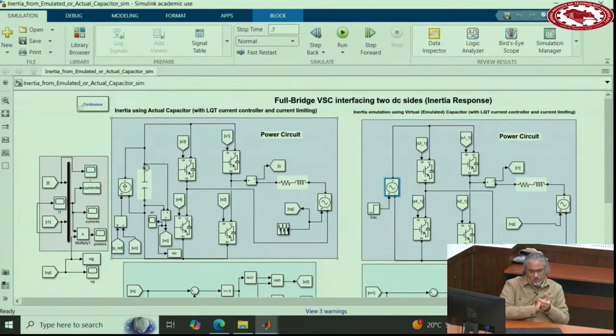Those types of systems are called hybrid systems in this context. But you need to justify why you want to do that. Is just using a battery there for the sake of inertia better than using a larger capacitor? Because in an AC grid, you want to maintain frequency stability, and the actual capacitor cannot provide that. So if it's a double stage and you really want to provide frequency support, yes, that is a good scenario for adding that battery.